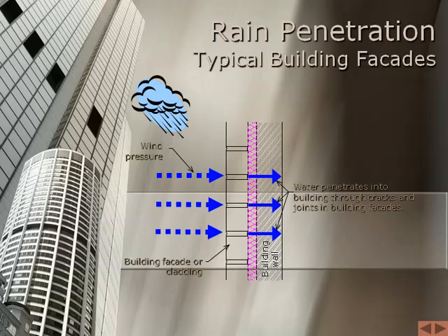Again, traditional methods for preventing rain and water penetration have concentrated on eliminating the openings that provide the pathways into the building. However, as water can pass through even the smallest hole or crack, the outside of the building must be perfectly sealed. This approach, the face seal, is a difficult condition to achieve and difficult to maintain over time. An example of a face seal approach is exemplified in some EIFS and stucco wall cladding assemblies.